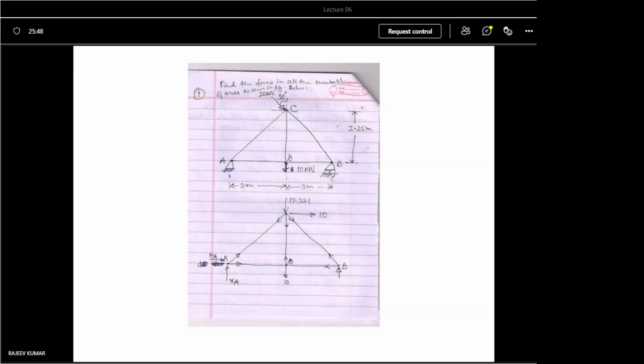And second, members are straight. All members are straight. There is no bending in that. You have also seen this in airport structures. And displacements are very, very small. That's why we are putting the roller supports. Whatever displacement there is, it will just slide.